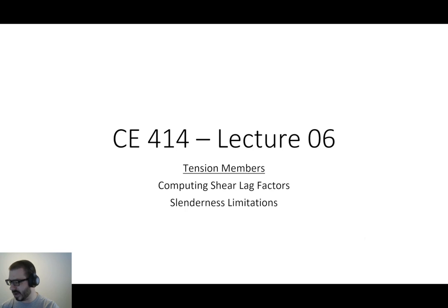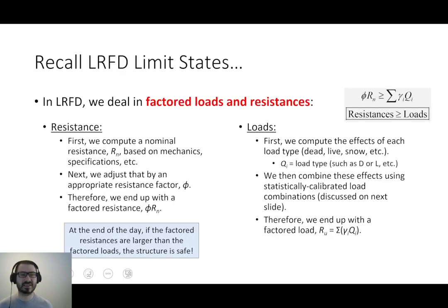Okay. Now, in order to set the stage, let's go back to some fundamental parameters which define what we do as structural engineers. And the first is the limit state, and particularly the LRFD limit state. So what we're dealing with is factored loads and factored resistances. So remember, on the load side, what we're doing is computing each of those individual load components and then factoring them, 1.4 dead, 1.2 dead plus 1.6 live, etc. And then we take the worst case factored load that we then compare against our factored resistance.